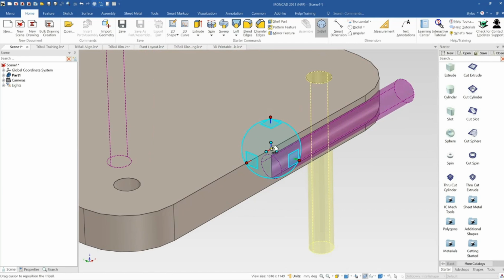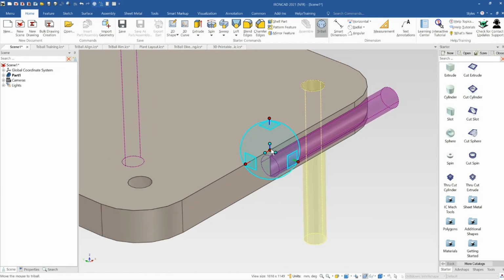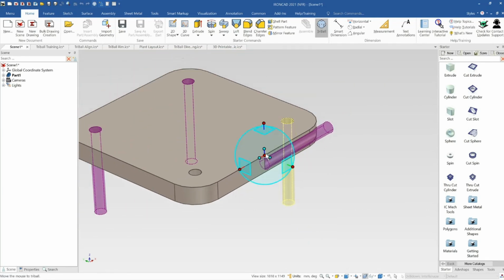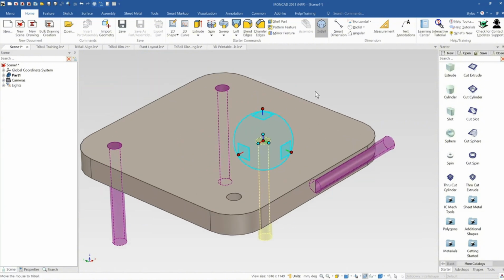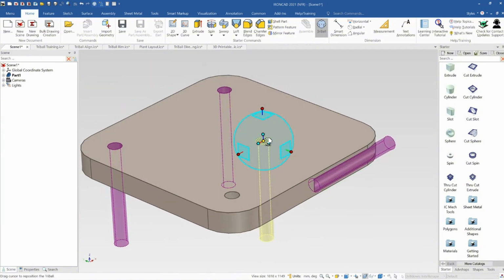Okay, now let's move on to the center of the triball. And this is likely the most powerful area of the triball. I'm going to reposition the triball here just quickly and then show you a few different options using the center of the triball here. As you can see, we can simply drag an item around using the center like that. It's really quick and easy. We can reposition it. We can hold down the shift key and snap to different points like that midpoint of